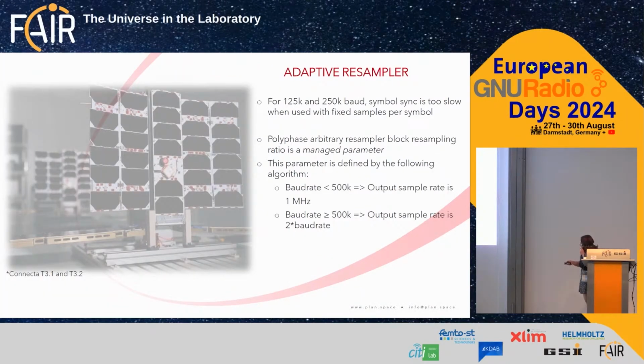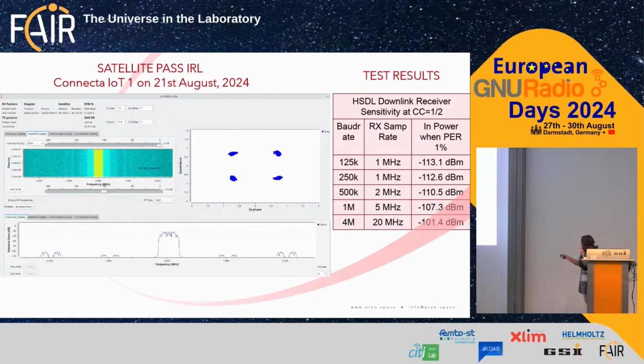Yeah, it depends, because if you see the end result at 25 kilobaud, my sensitivity level is actually 2 dBm off from what it should be. I used to fix all of the sample rates to 5 mega, and it was working perfectly fine. However, you see there are some issues. For the lowest baud rate, there's an issue here. Is that an answer? Okay, thanks.